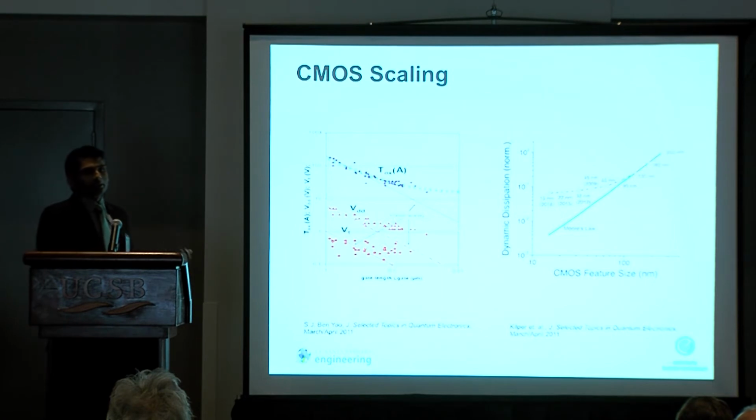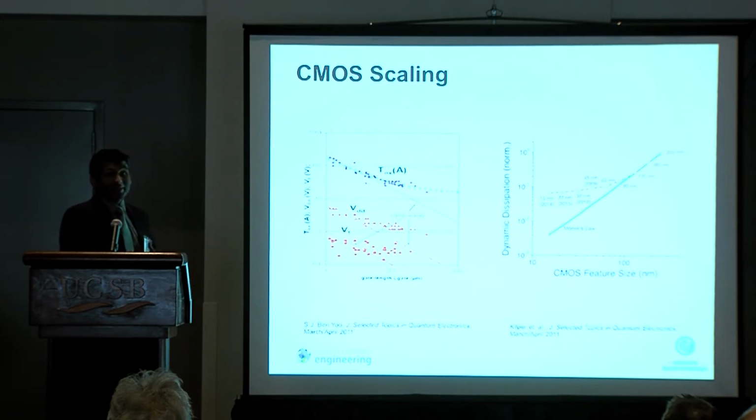Let's look at nanoelectronic circuitry. How is this going to help us? If you look at classical transistor scaling, this is the projected trend of how gate lengths will shrink, and how the supply and the threshold should shrink. It looks pretty linear, but in reality it starts to taper off, and a lot of this is because of the leakage present in transistors. Leakage in gate oxides and, at the nanoscale, tunneling effects prevent you from doing the classical scaling, which hurts you because you're not going to get the power savings that you would think you'd get by just scaling to a smaller, finer feature.